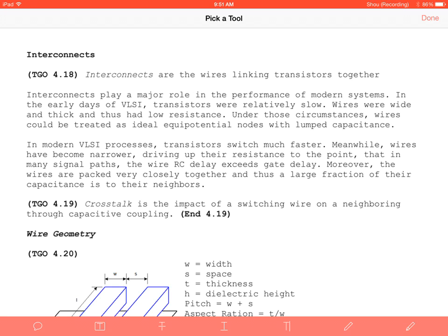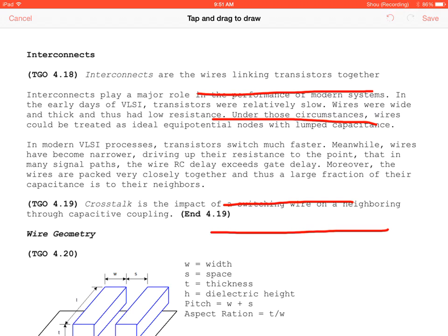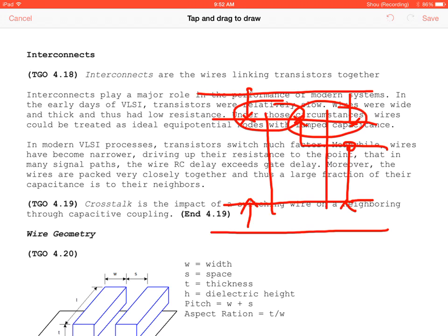So say you drew a 2-input NAND gate, and you have your VDD, your ground, your P diffusion, your N diffusion, and then your poly A and B. Then you have your output, and your N diffusion goes out here. So we have poly, and our transistor widths are here and here, and our transistor length is here.